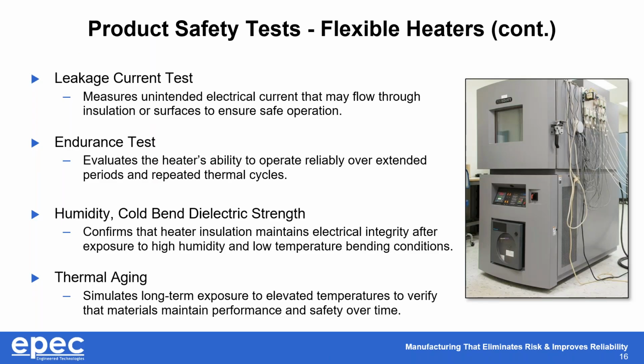Similar to some of the MIL standard and RTCA DO-160 tests, humidity testing is just as important to make sure that the heater does not break down after exposure to elevated humidity levels and low temperature conditions. The heater is then bent and manipulated to make sure that the heater still operates and doesn't create a hazard.